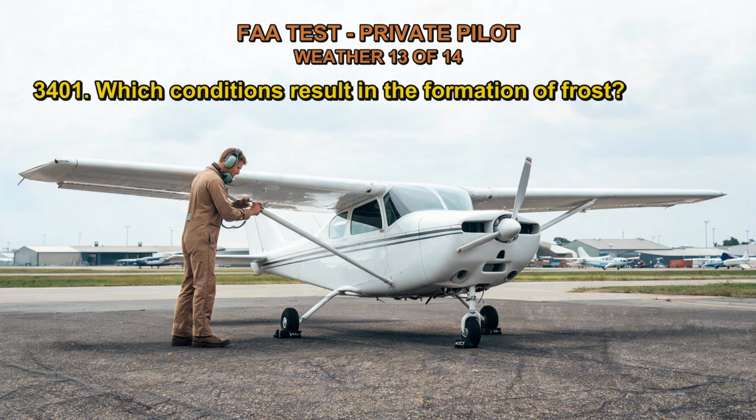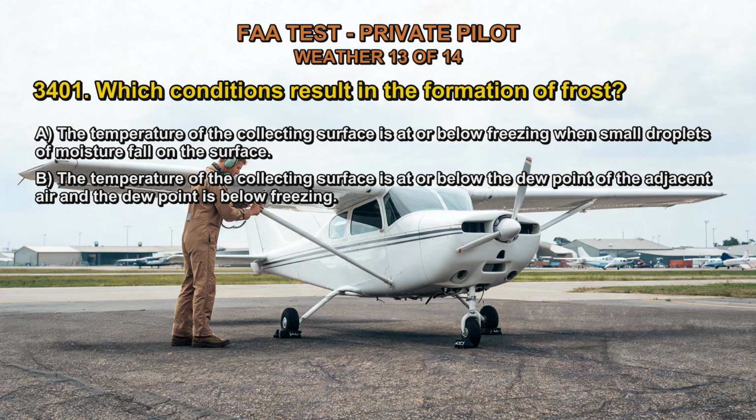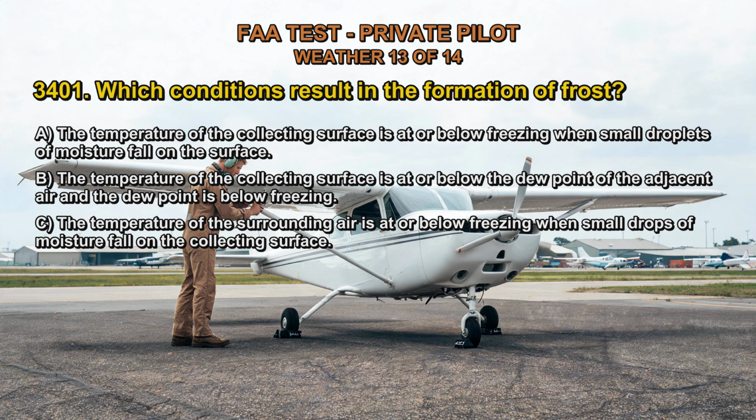3401. Which conditions result in the formation of frost? A. The temperature of the collecting surface is at or below freezing when small droplets of moisture fall on the surface. B. The temperature of the collecting surface is at or below the dew point of the adjacent air, and the dew point is below freezing. C. The temperature of the surrounding air is at or below freezing when small drops of moisture fall on the collecting surface. The correct answer is B.